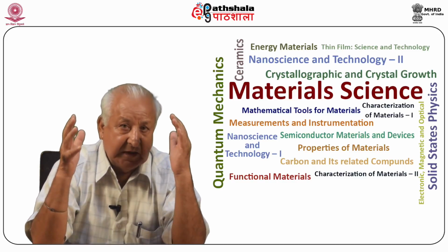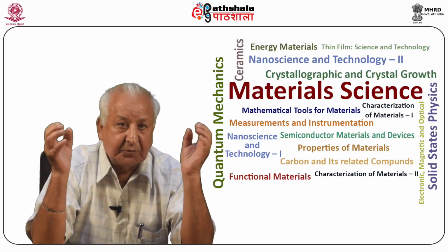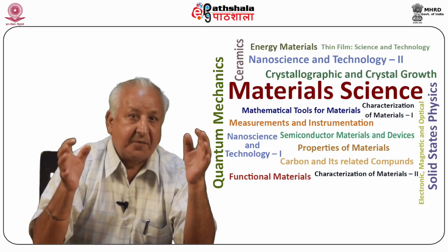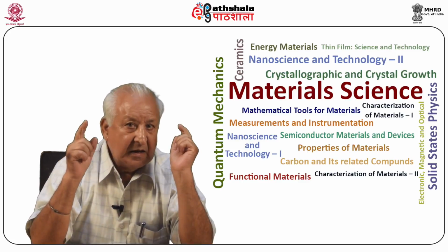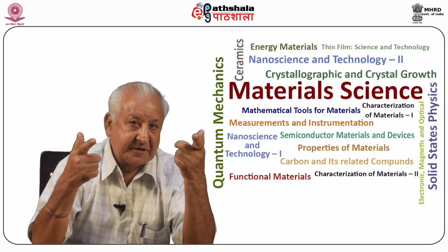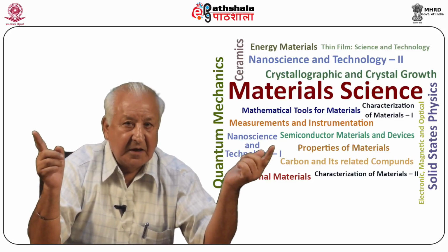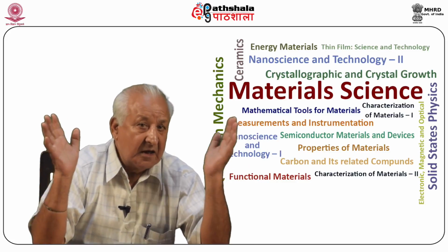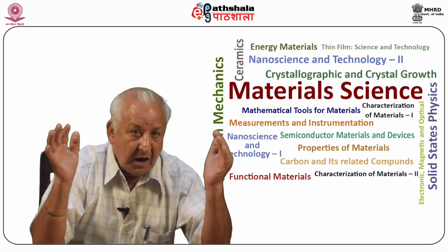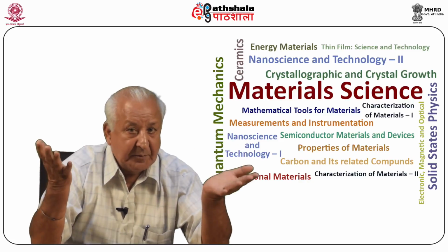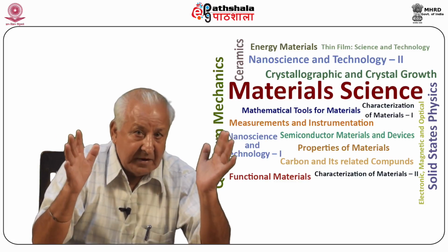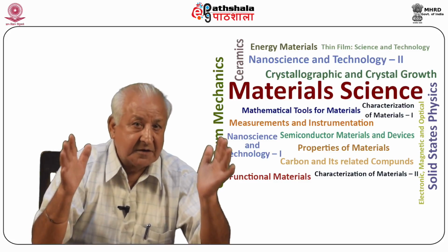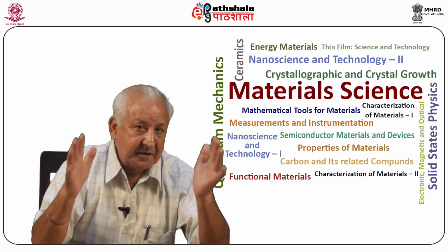The basic purpose of EPMA is primarily to provide quantitative chemical analysis, whereas the image formation is of secondary interest. In SEM, the situation is reversed because the primary aim is to provide image formation, whereas quantitative chemical analysis is of secondary concern. However, both these instruments are competent enough to provide complementary information and advance our understanding of the material under investigation.